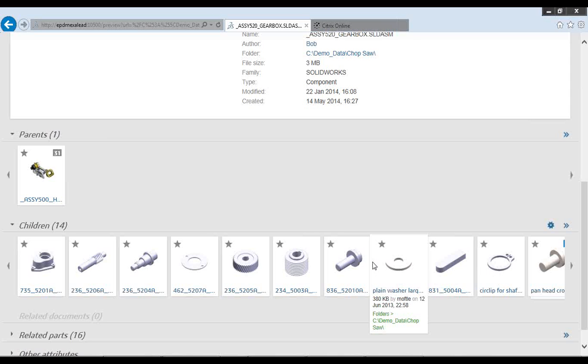If you have a lot of data that has broken references, you can actually change the scheme in which it finds the mappings. EXALEAD will know about the children, but it may not find them where they were last saved. Well, you can change the way the assembly mapping is done, and it will actually go and find them in places that it's moved to.